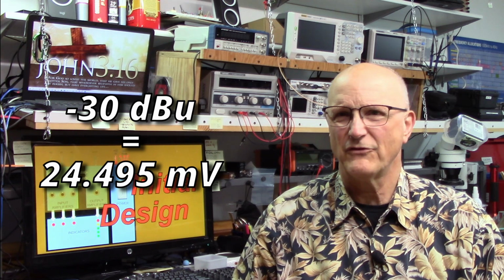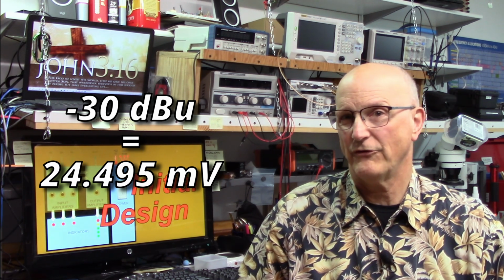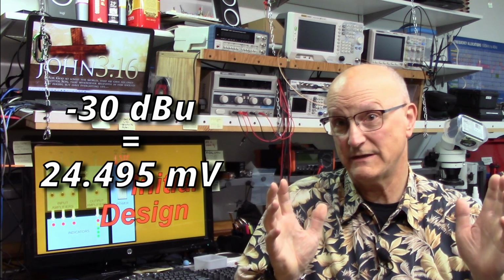As I said in the introduction, the output level meters actually indicate the average signal level, not the RMS voltage. One of the levels that we have to be concerned about is minus 30 dBu. And this is a relatively small voltage. It amounts to about 25 millivolts. So it would be real nice to have some gain associated with whatever we use to give us the average